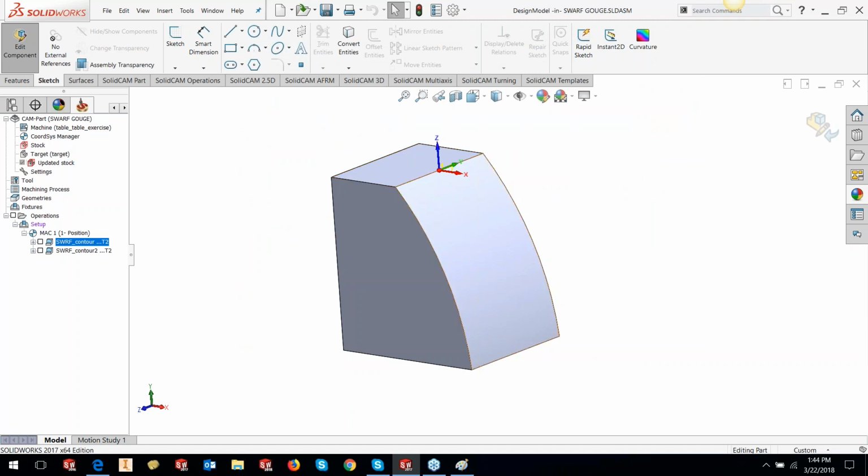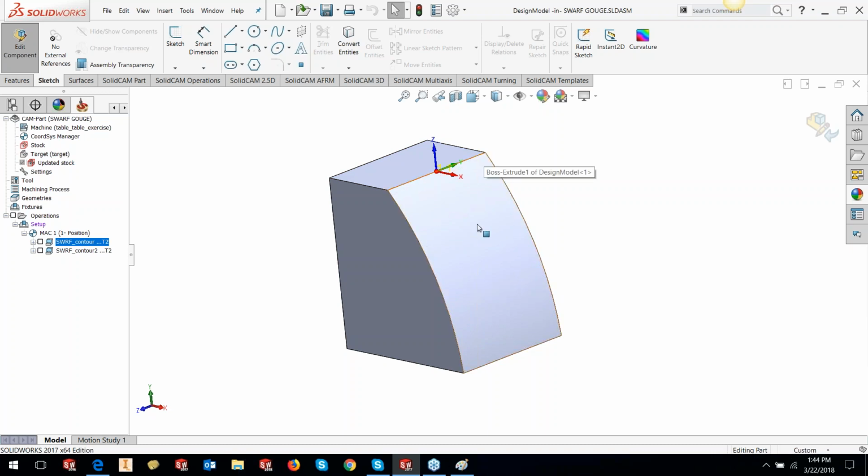That's the reason. But anyway, if I had to look at how the triangulation would get formed here, I could get one triangle, 2, 3, 4, 5, and sometimes 6 triangles. These triangles are generally not enough in some cases for swarf to find the perfect alignment between the upper curve and the lower curve, the 2 points that it tries to find.